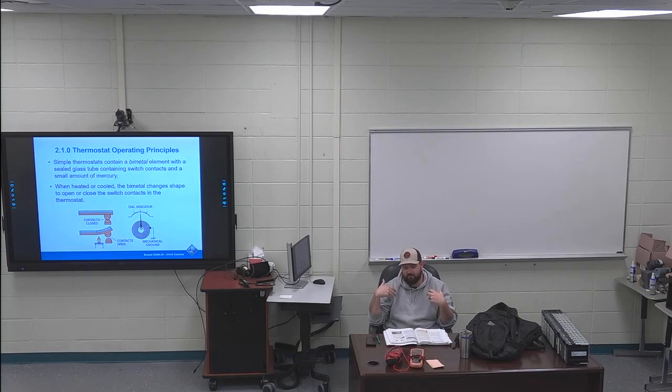A lot of us down here in the South don't even know how those systems work, but in big buildings and stuff like that, it's way more efficient to have a boiler unit and run heating, base for heat, around your house than it is to use electric heat. It just doesn't keep up. But the bad part about this is it's very slow reacting temperature-wise. So if you want a certain temperature in your house, you can say get up to 70 degrees. Well, it gets up to 70 degrees and it cuts off the heat to the boiler, but that doesn't mean the water inside this boiler is cool. So it is still putting hot water through, and it can get uncomfortably hot in the room.